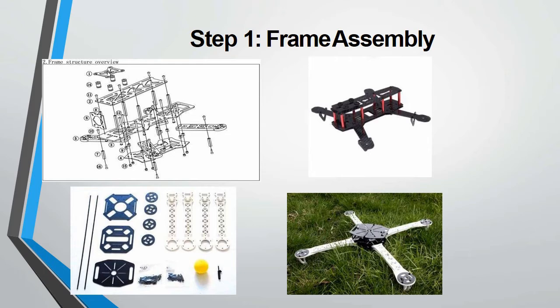So if you select wood for the frame, find a wood board that is longer than 60 cm and about 25 to 30 mm thick. Cut up this board in such a way as to get two laths which are 60 cm long and 30 mm wide. These two lengths are required to make the structure of your future quad. Crossing these two laths, you will make the X frame, like this, X frame.